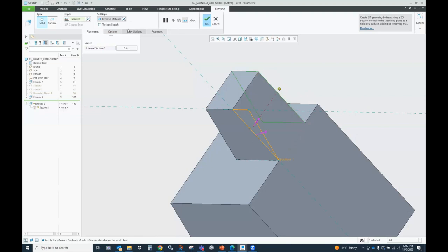Now, the nice thing about to reference or to selected, depending on what version of Creo you're using, is that as you're dragging this drag handle around, if you hold your shift key, watch what happens to that icon. It changes, right? That's telling me it's looking for something to snap to. I just have to drag it to that surface and let it go, and it's automatically doing the to reference for me. So that's the nice thing about that. The reason is that to reference is really one of your most robust choices here.